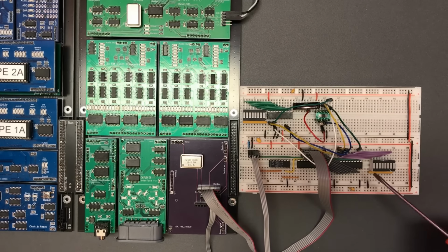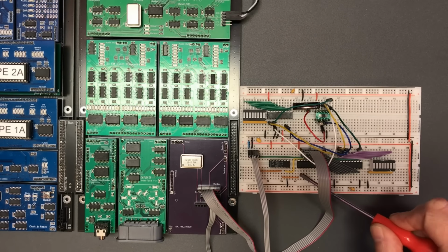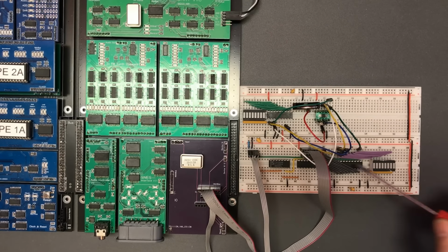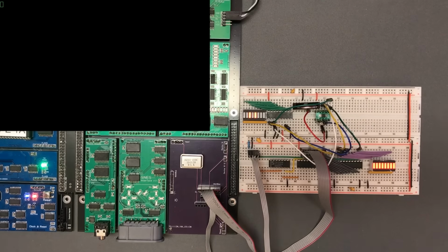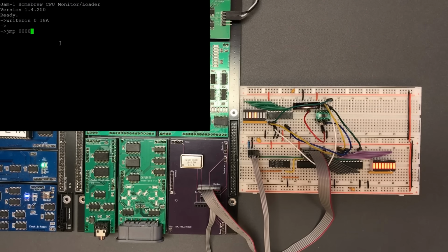So here's the I/O boards. We've got 8 bits of input. We're only using 1 bit at the moment, and we've got 8 bits of output, and we've kind of got that plugged into a few different things to implement the SPI interface. Let's power it on. So I'm going to run the time code. This is going to read from the real-time clock, and I'm running this at 8:48. Bang on. Now, I did set the clock again a few days ago, so I'm not surprised it's pretty close, but that looks like it's holding time reasonably well.